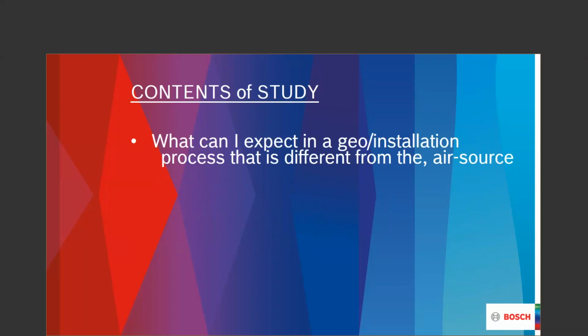So when you're looking at a situation from this, we can look at it and you can say, what can I expect in a geothermal installation process? Where is it different from the air source? Well, one of the things is you got to look at ductwork is ductwork. The other thing that we have to look at is the physical size of my geo indoor unit, what we would call the package unit. That package unit is not like a regular air handler in that it doesn't have a top and a bottom to it for flow of air to basically pass through it.